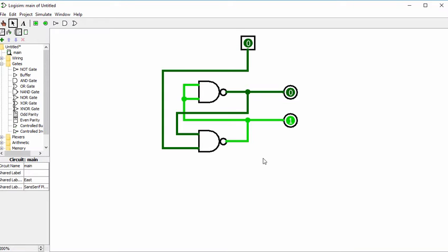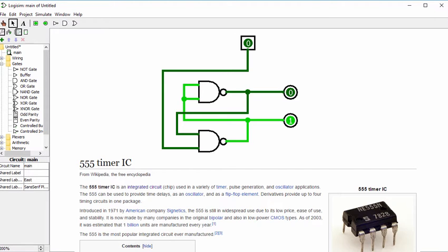The only real bistable element that's designed to teeter on the balance between 0 and 1 and 1 and 0 and just oscillate back and forth is called a 555 timer. And that chip, you hang capacitors on it and you can change the rhythm or the frequency that it oscillates in.